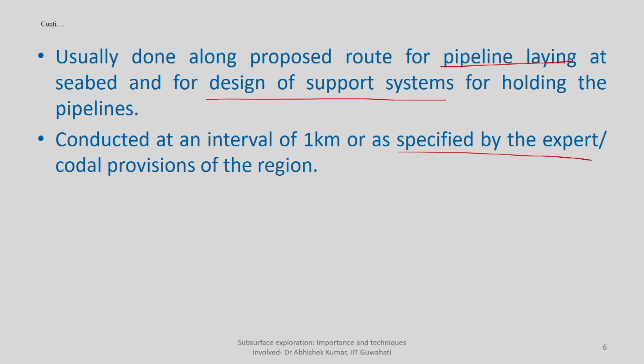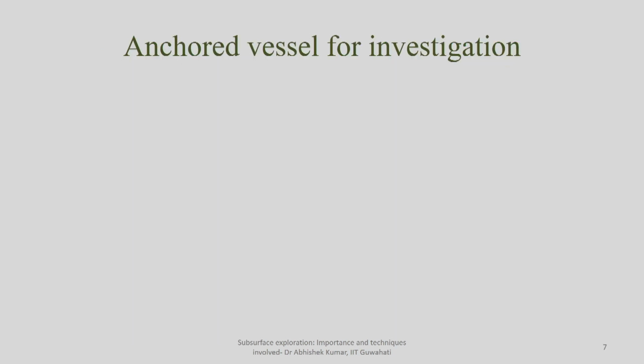...which are adding more and more complexity to your foundation medium, or which are adding more heterogeneity to your continuous foundation medium. Sometimes codal provisions are also available, but those are again region specific. So, one can consult those codal provisions before deciding how many tests in 1 kilometer, or how frequently this kind of shallow geophysical geotechnical testing has to be done.